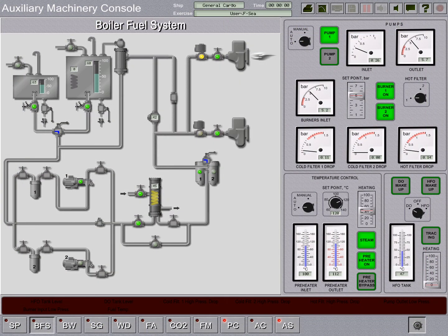To reduce the heavy fuel oil viscosity, it is subjected to heating. Preliminary in the heavy fuel oil service tanks and pipelines, satellite steam lines. Final in the fuel oil heater. The fuel oil heating temperature may be as high as 140 Celsius. To avoid the fuel boiling up, vapor and foam formation, the system maintains an operating pressure of up to 8 bars.